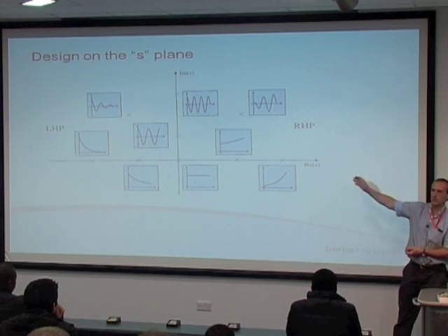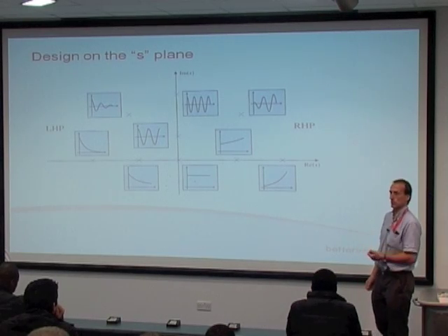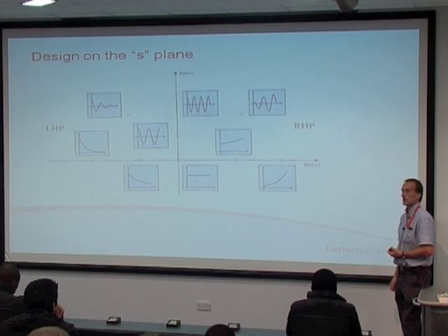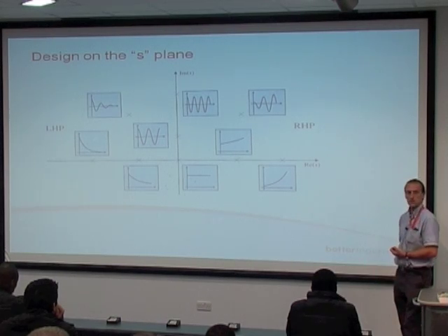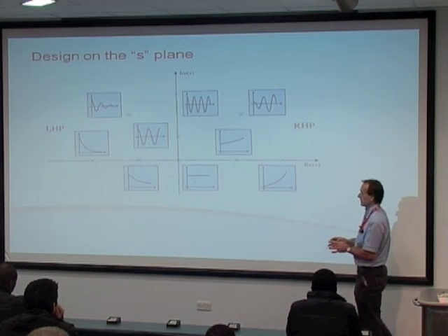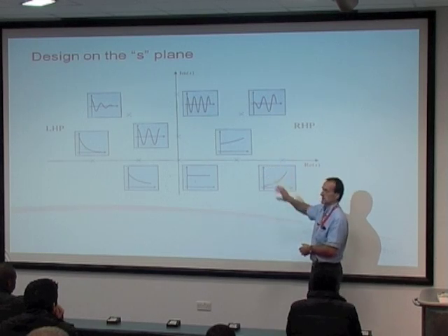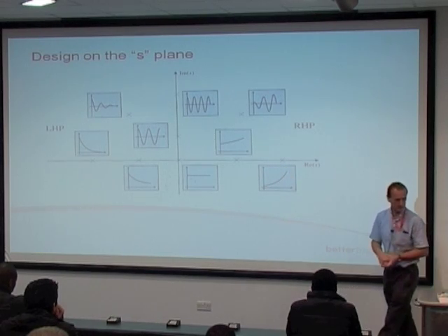If one of them ends up on the right-hand side of this, you think, well, I've got a big problem here, because my system overall will be unstable. Okay, and it's really quick and easy to see that. You don't have to work anything out particularly. Once you've got that polynomial factorized, you can very quickly look at the performance.